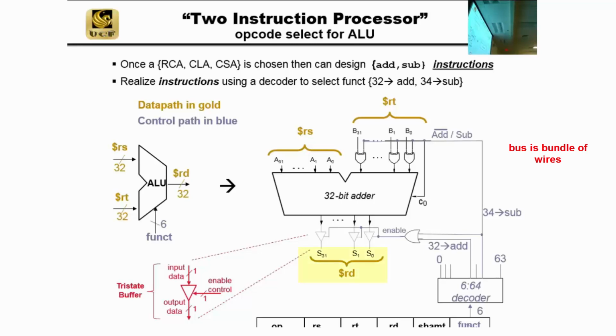So here's our bus. Let's call that RD bus, which is our data bus, the destination, and we connect that to it. It's wired up, and we have an SLL hardware in the data path, and it's connected up. And then we have, I don't know, a multiplier, XOR, or any instruction we want to build. What's the problem with connecting these together as a bus?